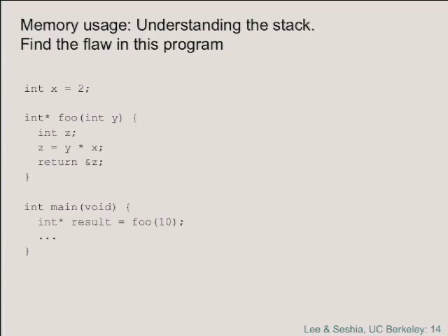Okay? You can't even count on a single assembly language instruction being executed all the way through. So if, for example, you have a multi-cycle instruction, you have an 8-bit processor, it's working on 16-bit numbers, you could get interrupted halfway through writing a value into a 16-bit variable. Okay?